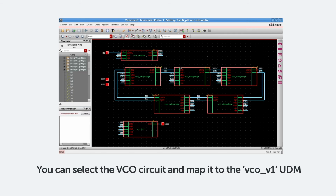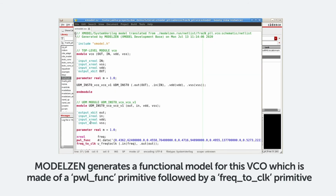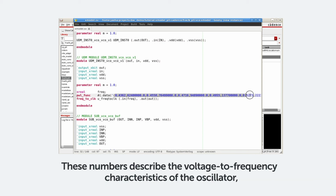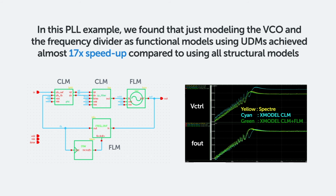You can select the VCO circuit and map it to the VCO_V1 UDM. MODELZEN generates a functional model for this VCO, which is made of a piecewise linear function primitive, followed by a frequency-to-clock primitive. These numbers describe the voltage-to-frequency characteristics of the oscillator, which is extracted from the SPICE characterization run by MODELZEN. In this PLL example, we found that just modeling the VCO and the frequency divider as functional models using UDMs achieved almost 17x speedup compared to using all structural models.